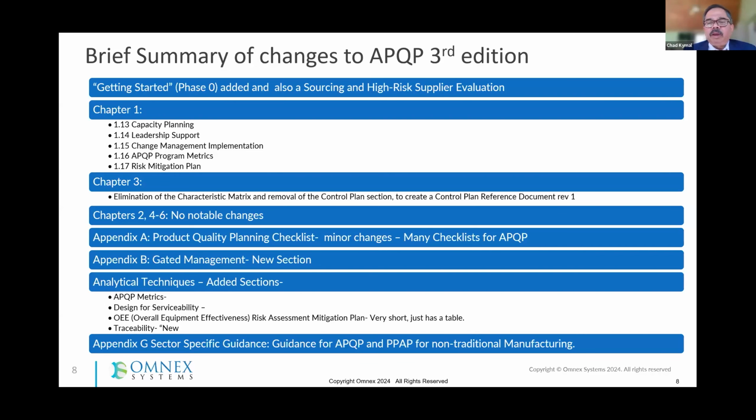I don't know if you all recall the characteristics matrix. Knew it, loved it, okay? It was actually more used with the process side of things. We had processes on the top and characteristics down the bottom. And it really helped you identify process characteristics which are important. You can say special process characteristics, like special characteristics, but coming from the process side. And I know many of us forget to identify the process characteristics in our control plans.